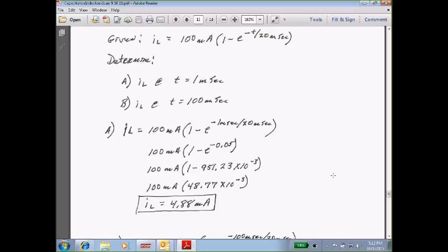The way they connect this, they take the 8 Henry coil in parallel with the neon lamp. Then I have them take the 9-volt battery, which is going to be in parallel with the coil and the lamp, but between the battery and the inductor, the coil, I have them put a normally open push-button switch.